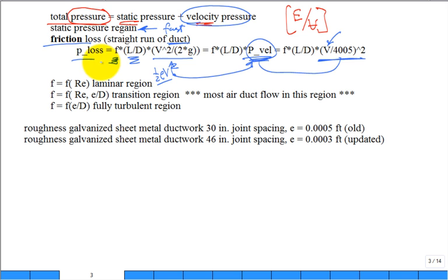That friction factor, could you get it off a Moody diagram just like for the water system? It's now just air through a duct. Yeah. Could it have a laminar region? Yeah, but we don't have very many laminar airflow systems. Okay. Could you have a fully turbulent region?